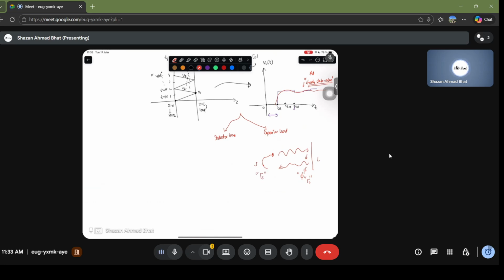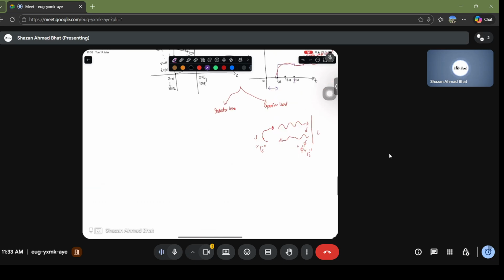Okay, so accordingly, let's say there's a pulse of waveform going towards the load end. If it flips in phase, it will look something like this and come back to the source. If there is a phase flip again at the source end, it will look back again like this, and it will hit, then it will come back, then it will go back and forth. So accordingly, it's how these voltage pulses behave with respect to it.